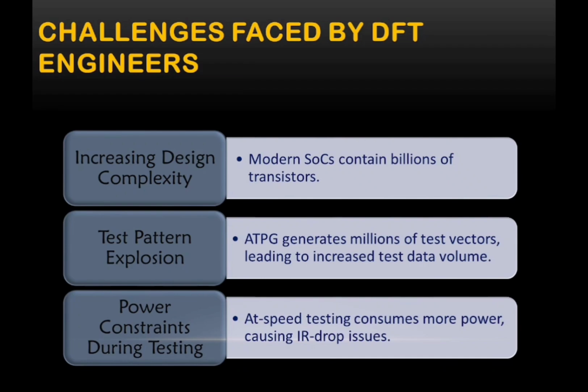So let us check what are the challenges faced by DFT engineers. The first and foremost challenge is increasing design complexity. Modern SoCs contain billions of transistors on a single chip, and advanced nodes like 5 nm and 3 nm require new fault models.